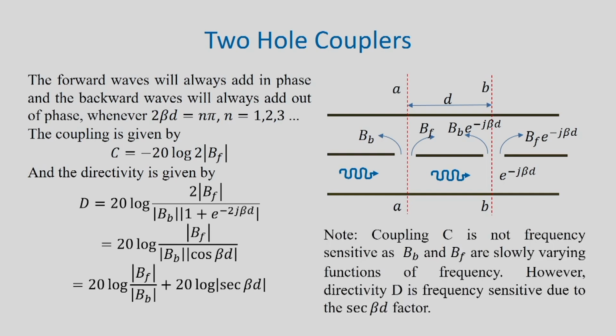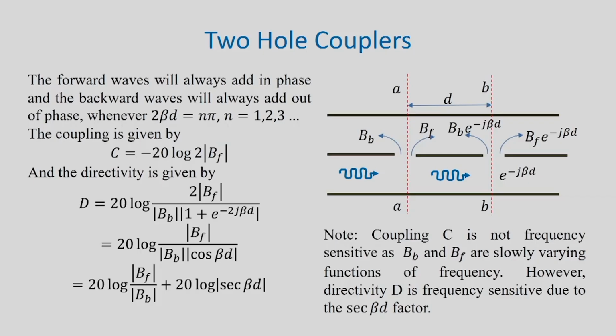We should note that the coupling C here is not frequency sensitive, as B_b and B_f are slowly varying functions of frequency. However, if we look at the directivity term, the directivity D is frequency sensitive because it has this factor sec beta d.